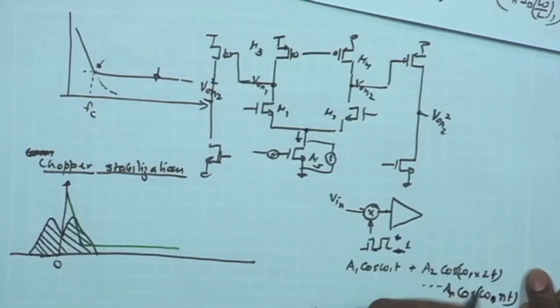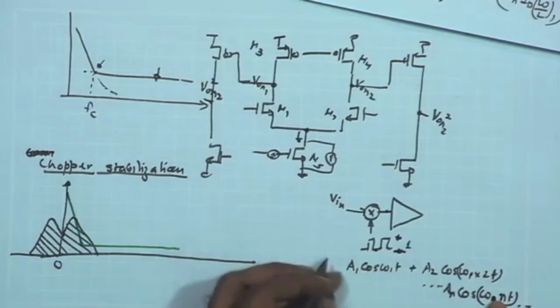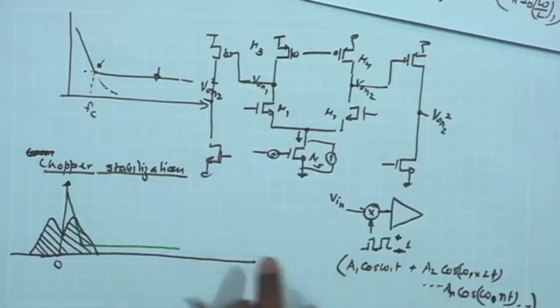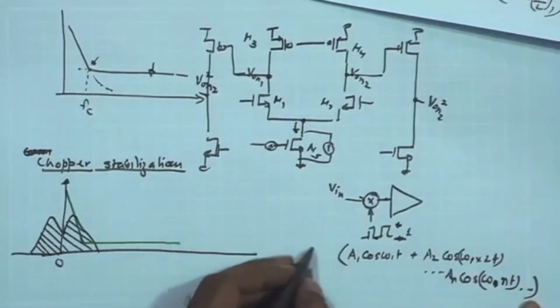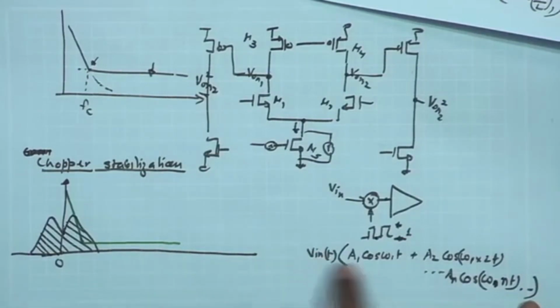And omega t and so on. So, we can expand it in the form of its Fourier series, and we can look at the coefficients, and when we multiply this entire quantity by the input signal, call it V_IN(t), which is having some spectrum, this entire frequency spectrum of V_IN(t) will be shifted to these higher harmonics and the fundamental harmonics of the square pulse.